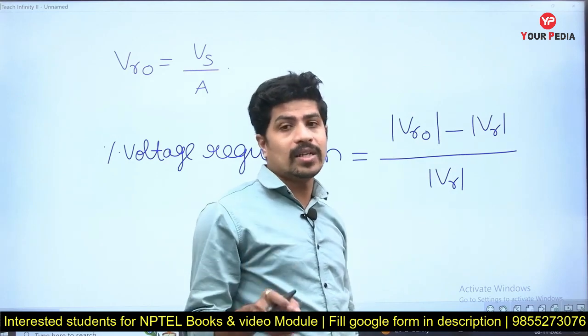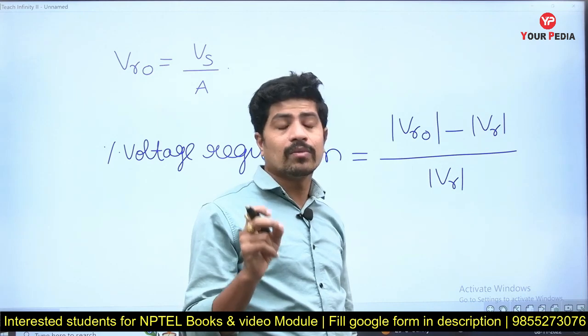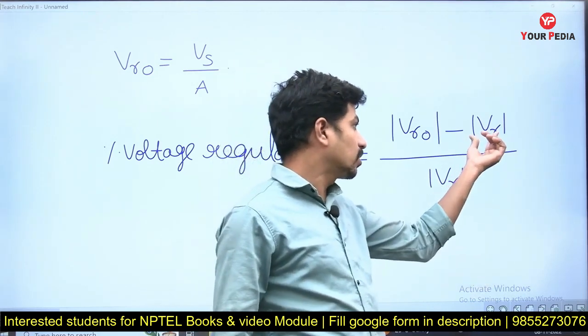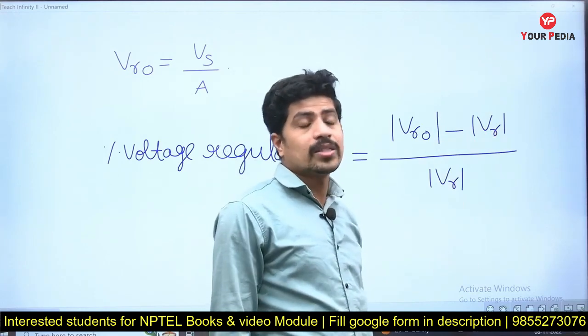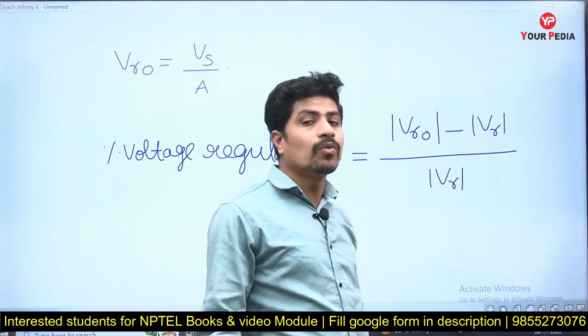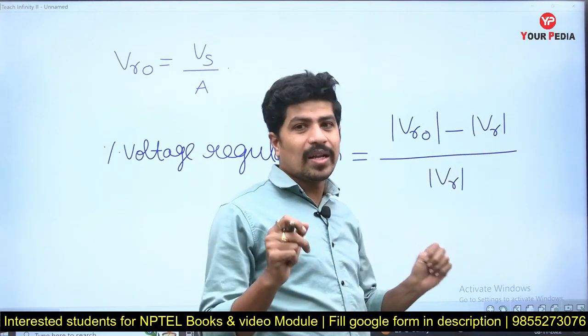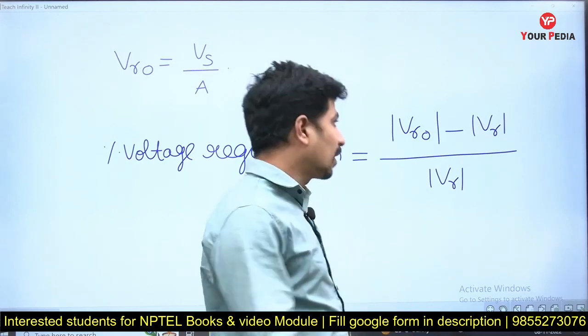While finding voltage regulation, we have to always take a load constant, meaning full load. This is for full load only that we have to calculate, and for the same power factor. If the power factor is leading during full load, the magnitude of voltage may rise. So there are many things to keep in mind while calculating voltage regulation.